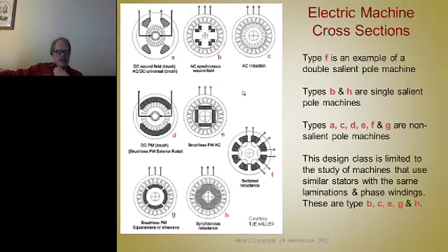That's better. The last thing I wanted to show you about this was of course the induction machine, which has the same stator as this one, but a different kind of rotor. And we're going to talk about what that rotor consists of. That's a punch lamination with slots in it, and those slots are filled with current-carrying conductors. There's a couple ways you could fill it. You can wind them, or you can cast them in there.